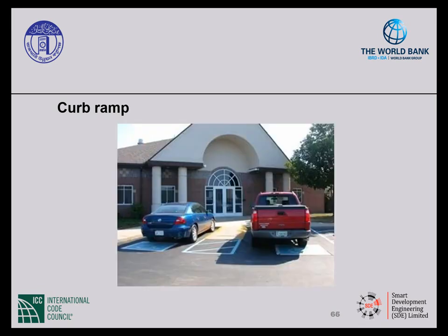So what about this curb ramp? Do you think it complies? Let's take a look. Here you have a painted curb ramp, which you would think would be a good thing because this curb ramp is projecting out into the vehicular way. However, as we said before, the painting on the curb ramp makes it slippery. Also, it appears that there's plenty of room within the sidewalk that the curb ramp could have been constructed there, so this would not be an acceptable allowance to let the curb ramp out into the vehicular way.